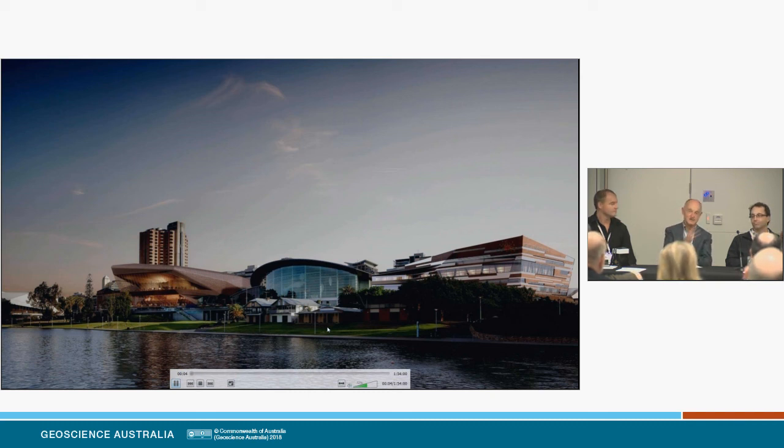Now, I didn't, in my rushed, garbled presentation, show everything. Based on the suspicion we had of that one at the east arm, I did have lakes over to the east that I didn't bother showing. We felt, okay, if we have a target at anything over 10 meters of optical bathymetry, we have that designated for doing conventional sonar or conventional bathymetry, whether that's through auger on the ice, at least spot checking in the winter, or in the summer.